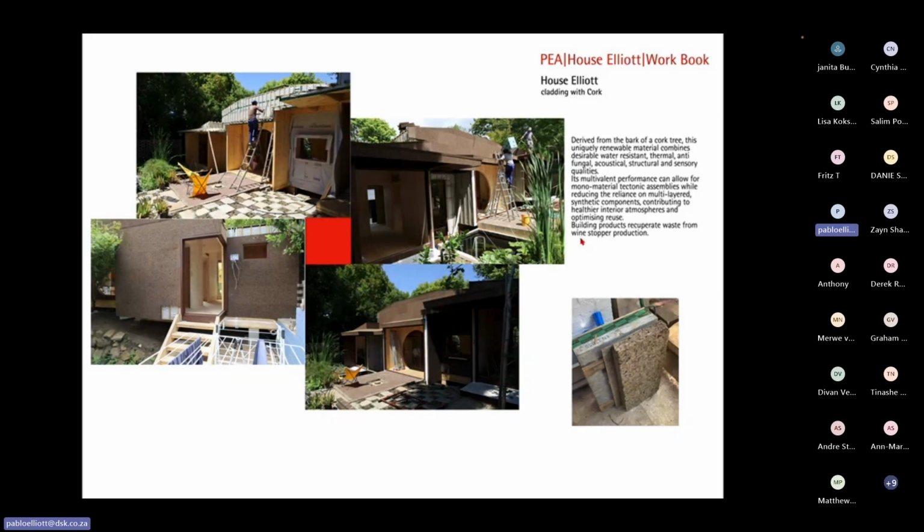But what they found in Portugal, where it comes from, because most cork oaks grow in Portugal and in Spain, they found that when they introduced the screw on top for the wine bottles, a lot of their market for cork stoppers evaporated, and they invented this way of making panels, in this case 50 millimeters thick, by using autoclave to bond particles of cork that are bonded or glued, held together with their own resin. So there's absolutely no chemicals involved here.